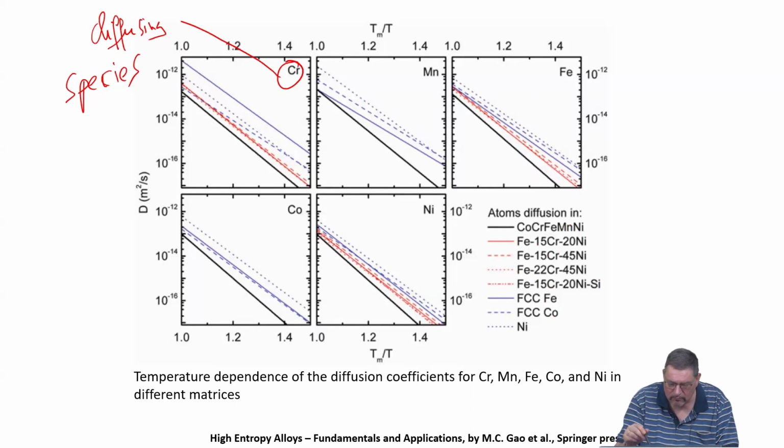So we have self-diffusion of nickel in nickel, and we have impurity diffusion of cobalt in nickel, and so on. How do you measure nickel diffusion in nickel? Only by tracer diffusion, right? So in one plot, interdiffusion and tracer diffusion results are compared. This is very complicated, or actually, in the way it is done here, not correct.